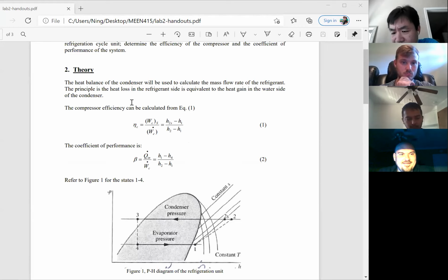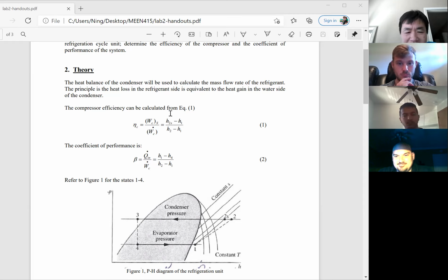It should be familiar to you, right? Yeah, you did this many times. I feel you should have in Dr. Chandra's advanced thermal class, for a refrigeration system, obviously you need to know the compressor efficiency. Every system, you need to know that. So this is the equation. Notice this is a compressor, so the subscript is 1 or 2 here between the compressor. Just follow the diagram. So it's the ideal, 2s, isentropic